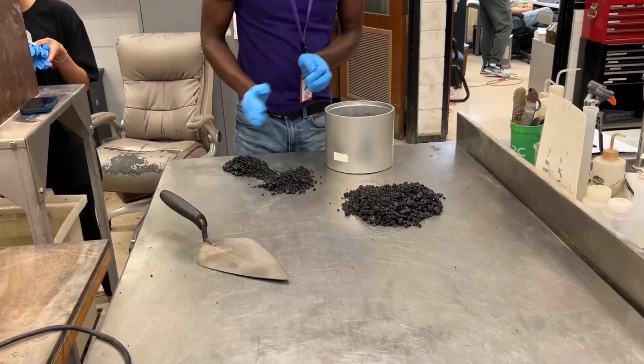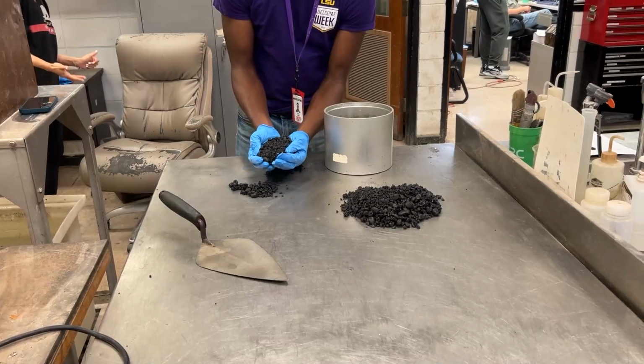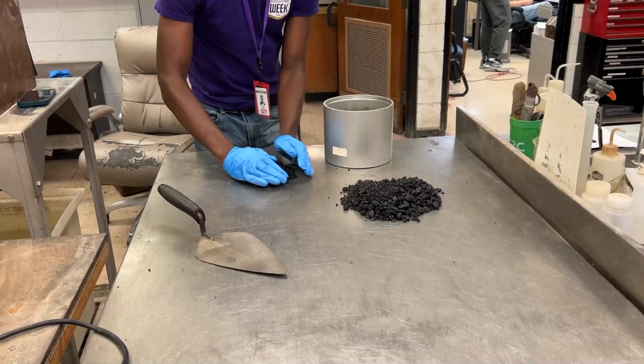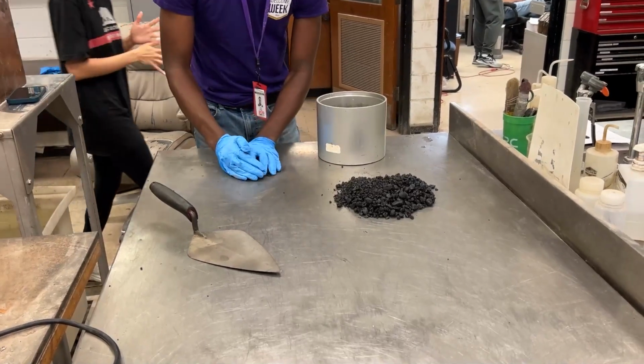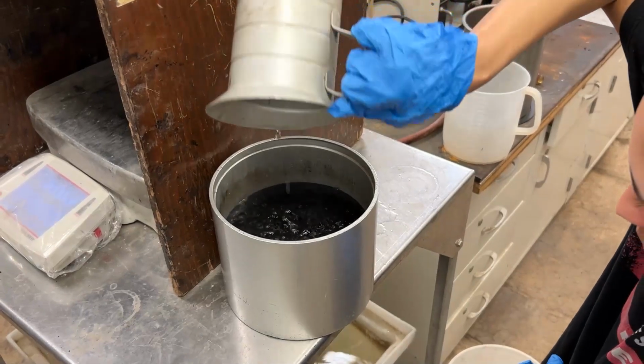These properties are used to calculate the percent air voids in compacted asphalt mixtures, provide a target value for compacted asphalt mixtures, and are essential in finding the amount of asphalt binder absorbed by the internal absorbency of the individual aggregate particles in asphalt mixtures.